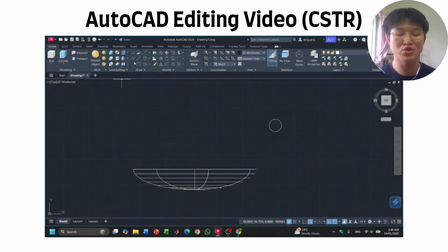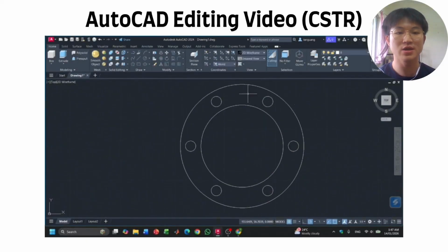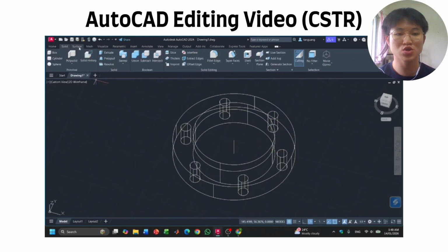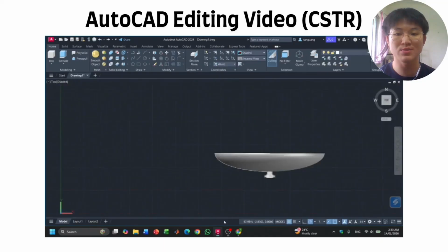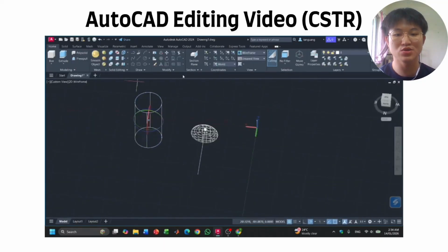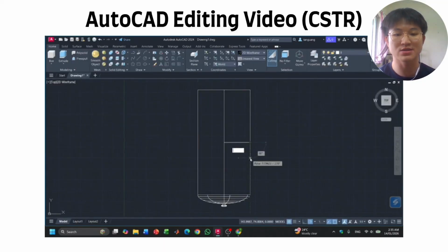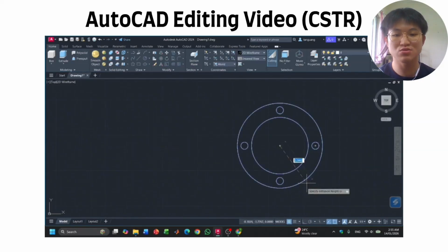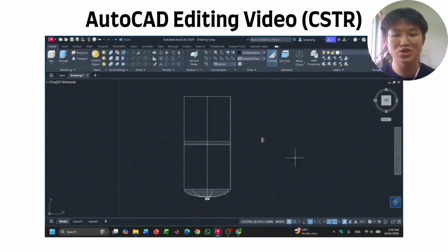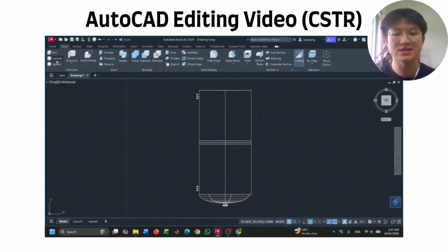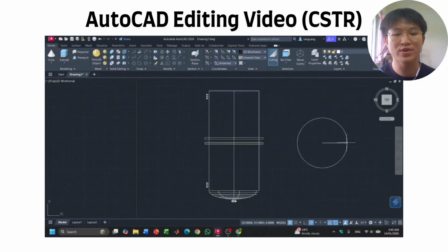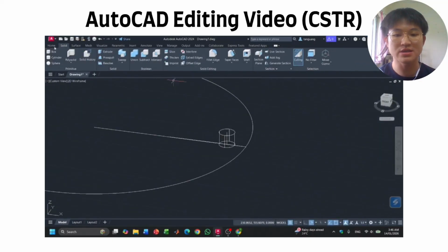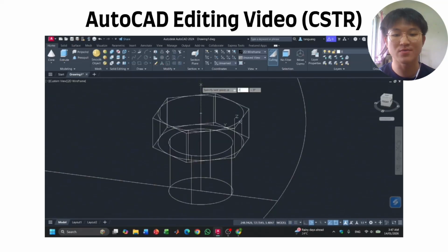In this project to produce 100 kg per day polypropylene, the most suitable reactor is CSTR, as most industrial polypropylene production commonly uses slurry phase loop reactors, which are also a type of CSTR. It provides uniform temperature and concentration with constant feed and steady state conditions to maintain consistent polymer properties. With the presence of an agitator, it allows effective heat control.